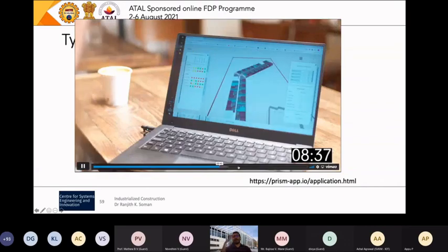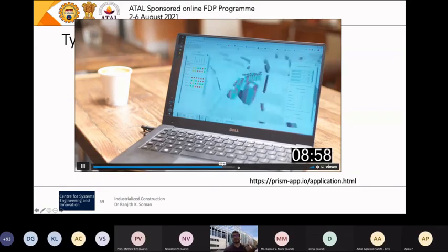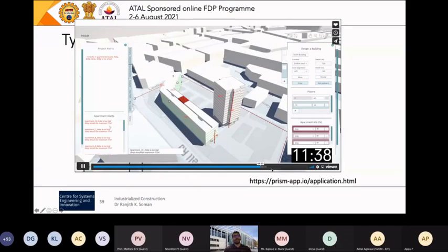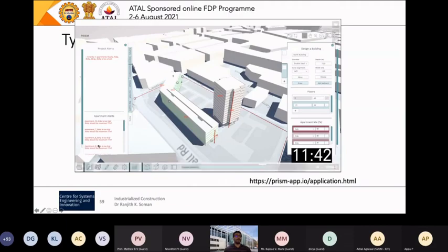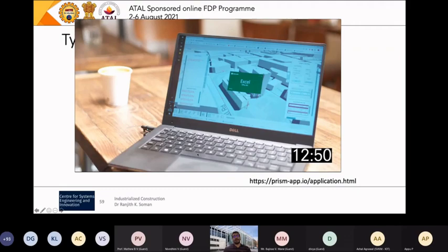All of this can be done within a tool, and it will come out with a bill of materials, which we could use for manufacturing. You have a project in the same platform, and some of these things came up as alerts, wherein some rules and regulations were not satisfied, all of this within a day for a very large apartment. And once you do that, you can export the whole thing as an Excel or whatever is required by your system.